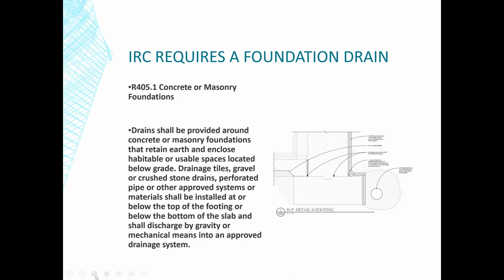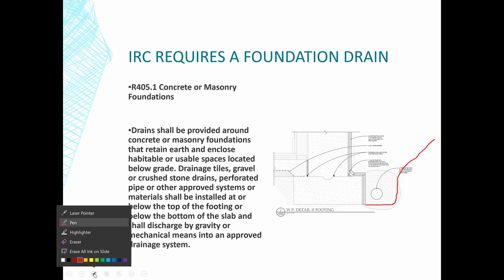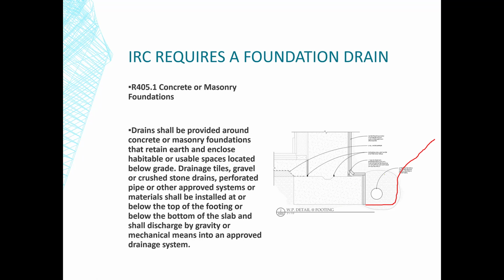Let's see if I can draw that. So the Mirafi fabric might go like this and then up the excavation and just be sitting there. And then all this gravel gets pushed into here. Or sorry, it would go to this level, then the pipe gets put on, and then it comes to the second level, and then they just fill it all up, right?